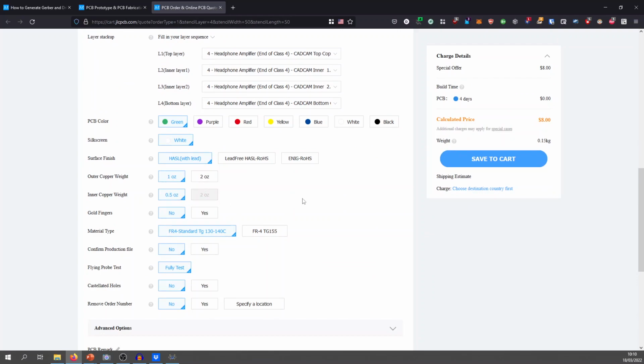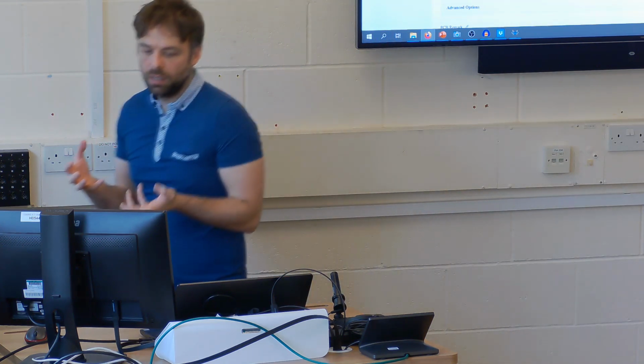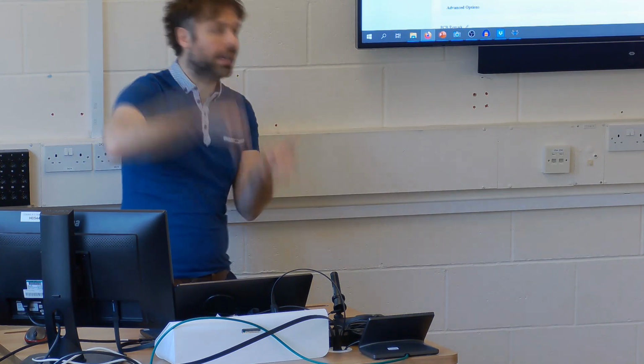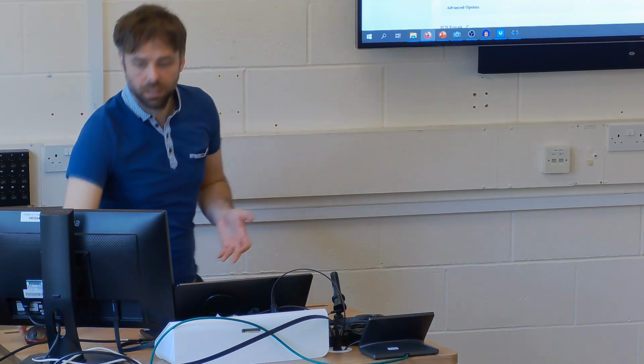There's a program. I've not got it installed. I'd have shown you. I'll show you next week. There's a program called Saturn PCB Tools. Has anybody heard of that? It's a program that's got a bunch of calculators all in one. It's got PCB calculators. It's extremely useful, and it can tell you, if you've got a certain weight of copper, thickness, wideness of trace, what the resistances are. It can tell you the resistances of vias connecting through traces. It can work out strip line impedances for you for a given type of FR4 that you're using.